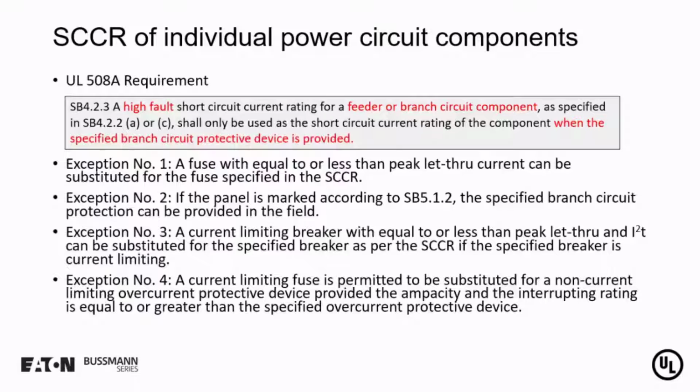So, for example, a 5 kA rating must be supported by a fuse or circuit breaker that has obviously a 5 kA interrupting rating, and typically that fuse or circuit breaker would be specified because it was part of a test, a short circuit test, to determine that fuse or circuit breaker properly protected the component. You do that for standard fault ratings and high fault ratings as well.